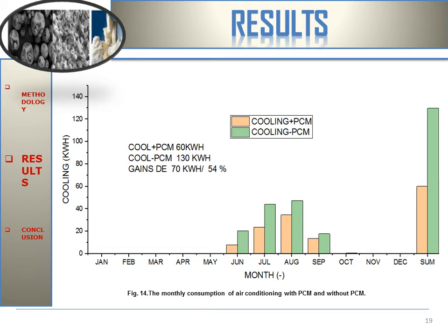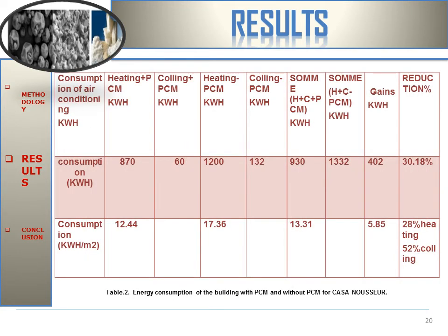Figure 4 and table 2 show the annual heating and total energy consumption. It shows that the walls with PCM require less energy for heating and cooling compared to the wall without PCM in all months of the year. PCM will reduce energy consumption by 25%, whereas without PCM the building consumes 311 kWh for heating and cooling, but walls with PCM consume only 240 kWh.